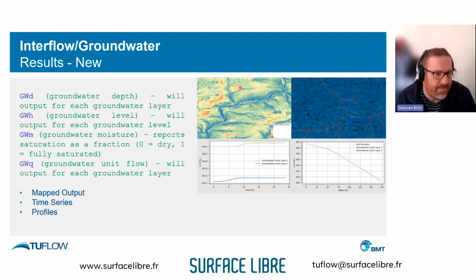So we can do some quite nice mapping actually of groundwater moisture within our soil layers, and identify those layers that are saturated. We can also use vectors. So in this instance, what we're seeing is the red lines is the surface river network. The black lines are the subsurface movement of flow. Forms quite a wider drainage network, really.